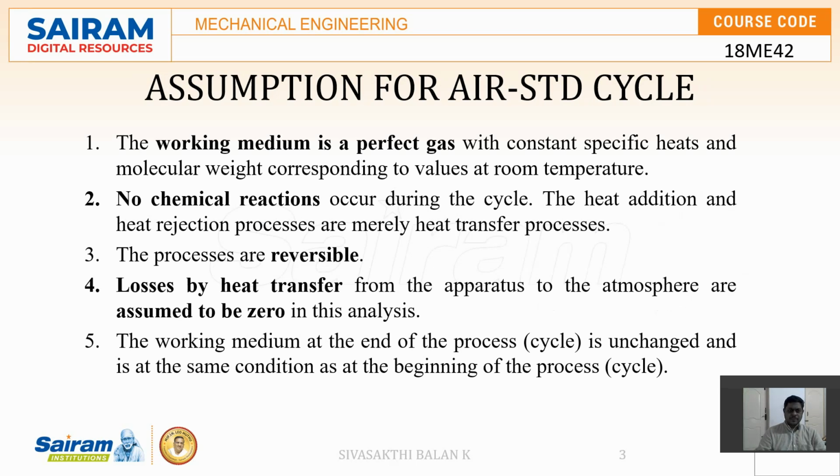The main assumptions are that the working medium we are using in the air standard cycle is a perfect gas, particularly air, and there is no chemical reaction during this cycle, and all the processes are reversible. We also assume that no heat transfer takes place between the system and the surroundings. That means whatever heat is supplied into the system is completely converted into useful work, or in other words, it should produce a 100% efficient engine.